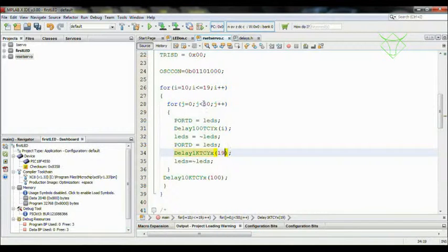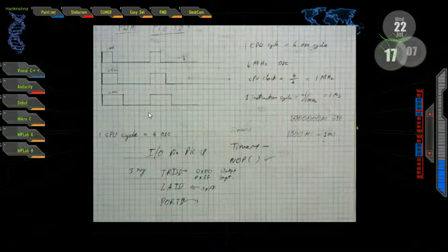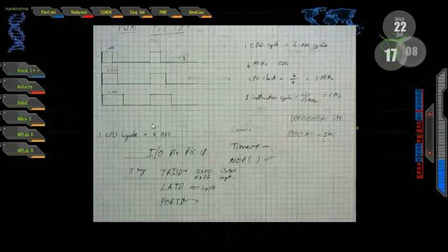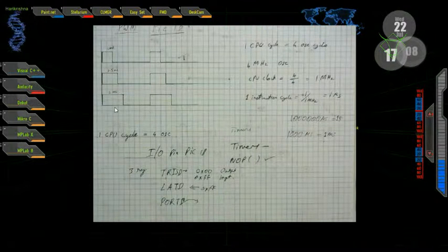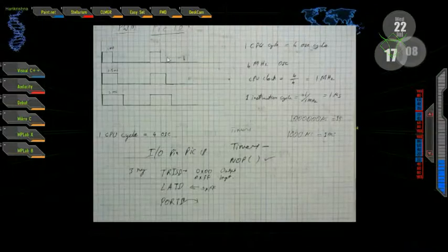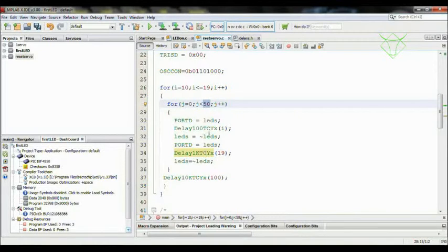This I am repeating 50 times because, in my previous servo explanation, I have told that I have to send this pulse 50 times. For 1 second I have to send this pulse 50 times. This 20 millisecond pulse period repeats 50 times for 1 second. So I have to send this for 1 second continuously for the servo to set itself to the correct position.